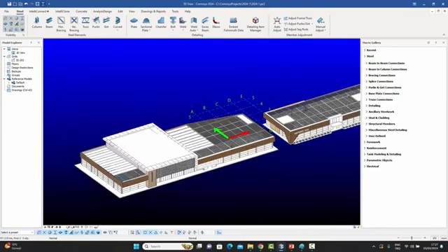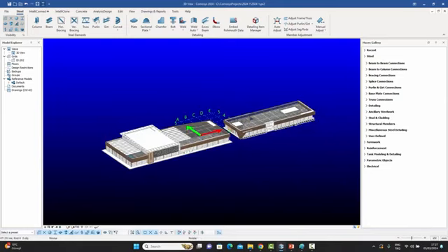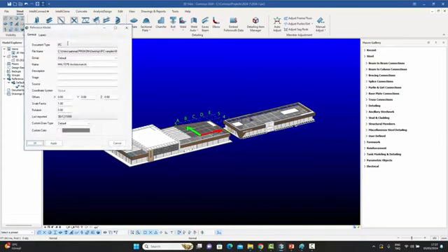The entire reference model needs to be acted upon by the user, and only things you want to do with the entire model are possible. So what are those things which are possible? If I open this now, you see we have this reference model listed under the default group. If I double click on that, you see that it's an IFC file. It tells you where the IFC file resides, and under which group, the default group. It has a name. You can add some descriptions and stages and sources, some extra information if you want.